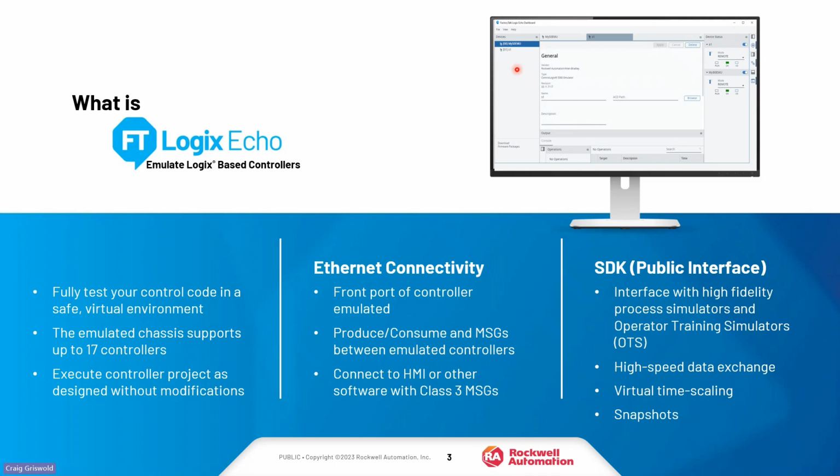I can create multiple chassis in here, which can hold 17 controllers. With the release having multiple chassis, one of the bigger uses is that most customers put their controller in slot 0. So if I use slot 0 up, then I've got to move my controller around. So I can create multiple chassis, and I'll show you this in a few slides and in the demo, to not only add capacity for additional controllers, but also to open up slot 0, which a lot of people use.